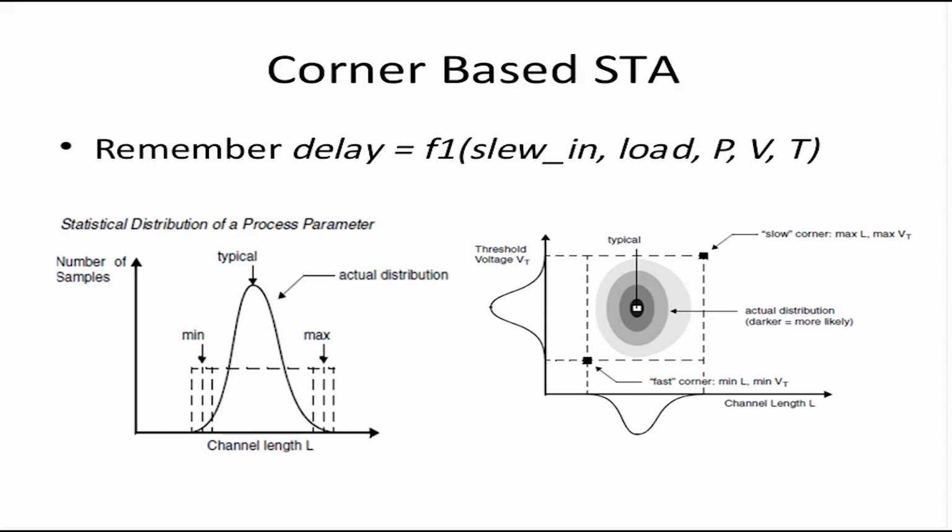So now the delay of a cell at the standard cell library level depends on the input transition and output load. We have seen that. So delay is a function of input slew and load, and for every technology, on every corner, you have one library. The delay will be characterized for each corner that we have chosen, so for each PVT. Ultimately delay depends on PVT. For one PVT there is one library. In each of those libraries you have a cell, and characterization is based on input slew and output load. So there are parameters there: PVT, slew, and load.